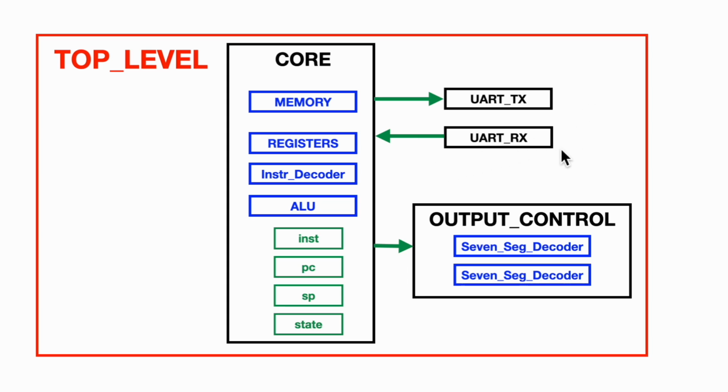In our implementation, we're just going to have one device. That is the UART serial communication. Actually, you can think of it as two devices because the transmit module and the receive module are really quite separate. But in any case, we will be using a single register for both the input and the output. We'll use register 0. So to write a character, we'll use an out command with register 0 to send a byte from the A register to the serial communication. And to read, we'll use an in instruction, and that will transfer a byte from the UART into the A register.